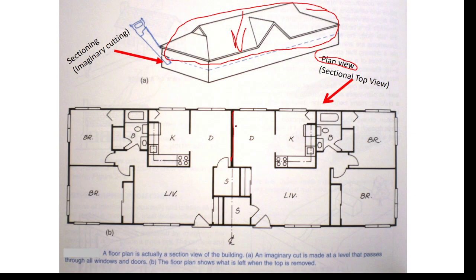But in some cases, if the scale of the projection is small, cross-hatching lines are not so distinguishable. It is even allowed to fill the surface with paint; for instance, black has been selected in this example.